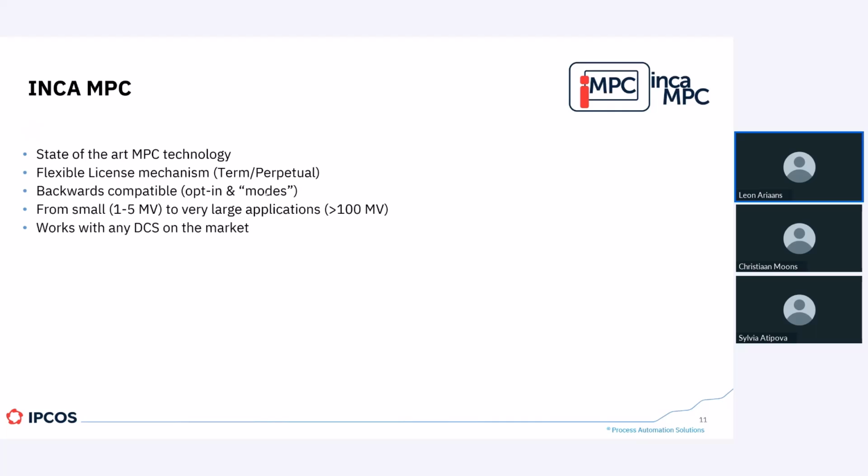INCA MPC works with any DCS on the market. Some integration work is required such that the switching logic, if you switch an MPC on the DCS, should have matching behavior. That requires integration work on the DCS. We actually also provide services to help you with that bit.